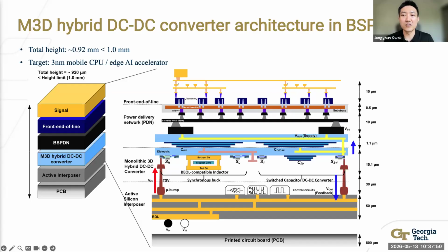Above the interposer is the back-end line converter layer with all the indium tungsten oxide power transistors, thin film inductors, and capacitors. The cobalt zirconium titanium inductor is the thickest part at 15 micrometers. Total converter height, including the interconnect, is about 46 micrometers.